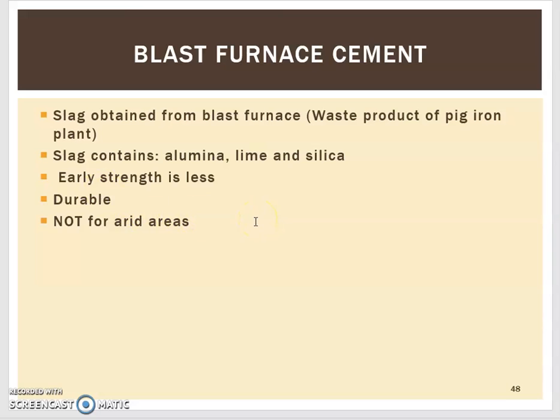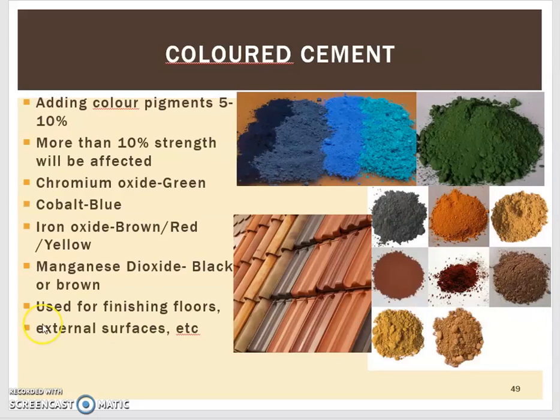It has a less early strength and requires a way longer curing period. Okay, so it will gain strength eventually, but you will have to cure it for a longer time. Okay, it is very durable, but it is not suitable for arid zones. What do you mean by arid zones? Arid areas are the places where the moisture content or humidity is very less. In such cases, this kind of cement is not suitable.